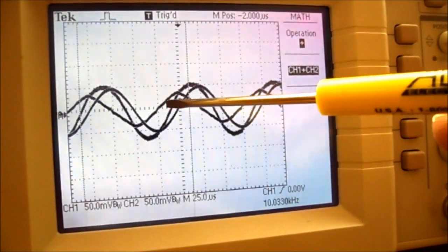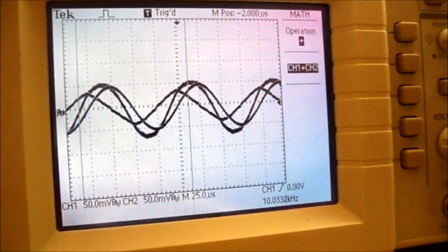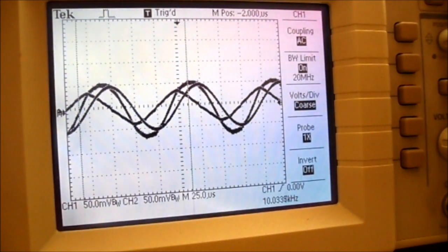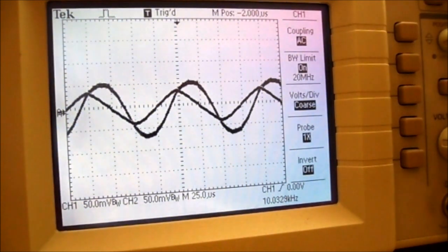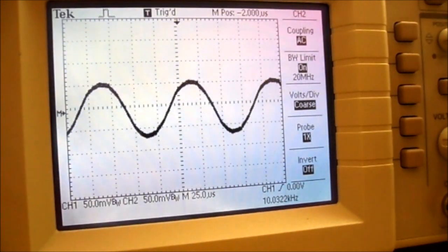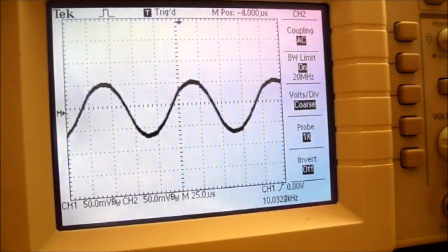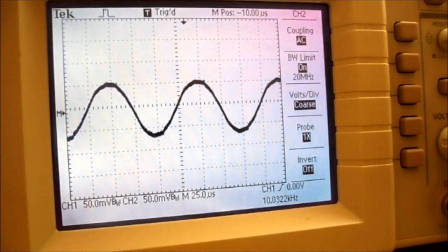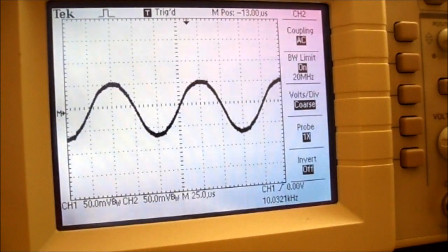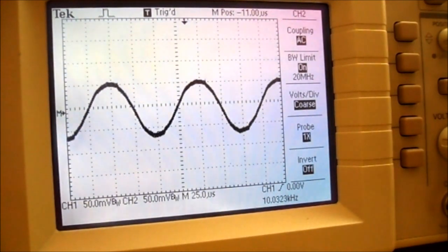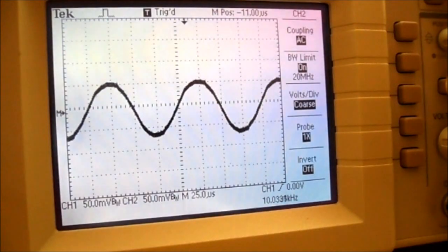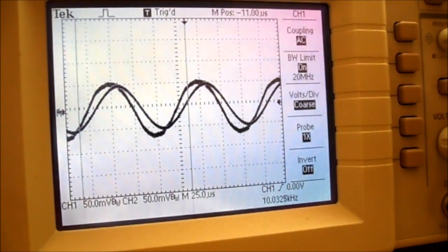Now it's very hard to see which one's the input waveform, so if you press channel 1 it brings up its menu, press it again, it turns off channel 1, press channel 2, brings up its menu, press channel 2 menu again, and it takes away channel 2. Now you can use the horizontal position to make this, which is VIN, right? It's channel 1 plus channel 2 is VIN. So center that line, then turn on channel 1 by pressing the channel 1 menu button, and bring in channel 2 by pressing the channel 2 menu button.